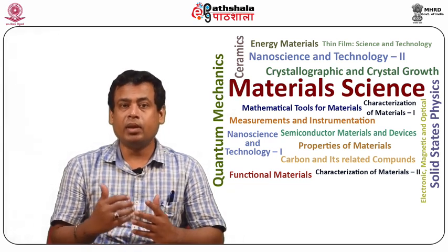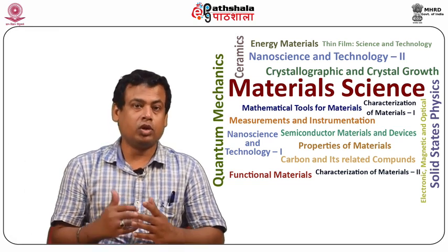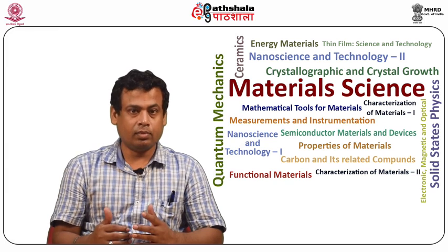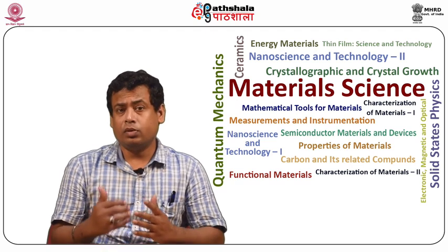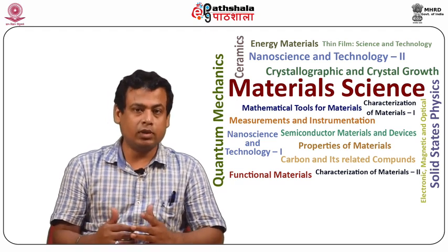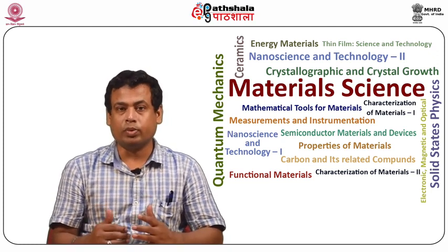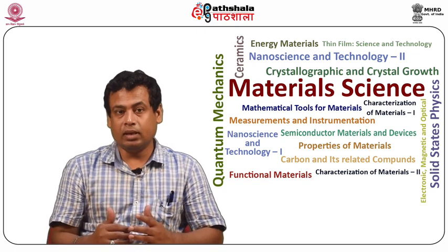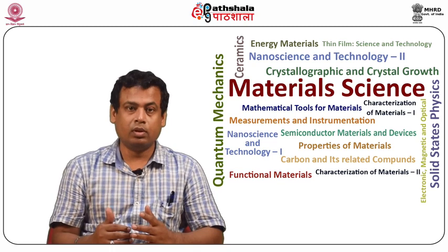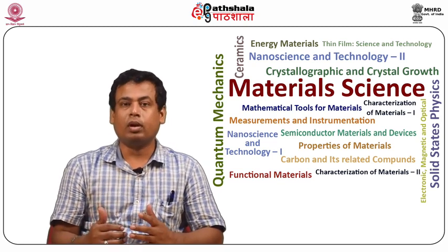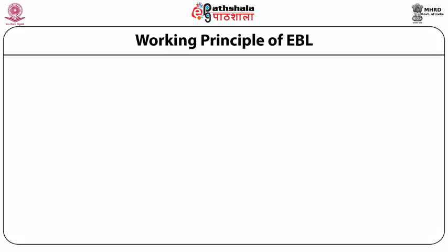Its primary advantage is its ability to draw custom patterns with sub 10 nanometer resolution. This form of maskless lithography has high resolution and low throughput, limiting its usage to photomask fabrication, low volume production of semiconductor devices, and research and development.